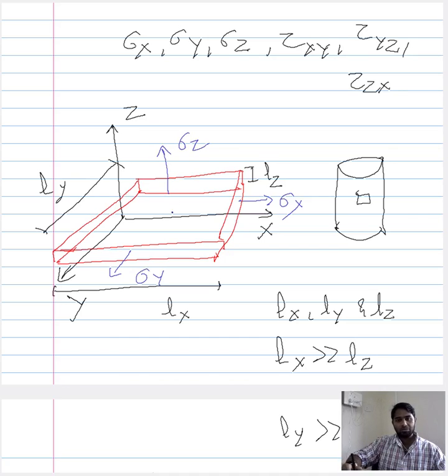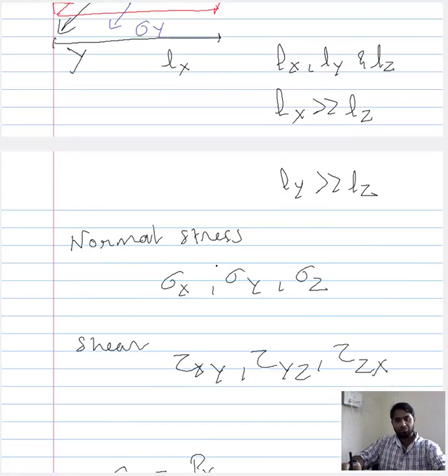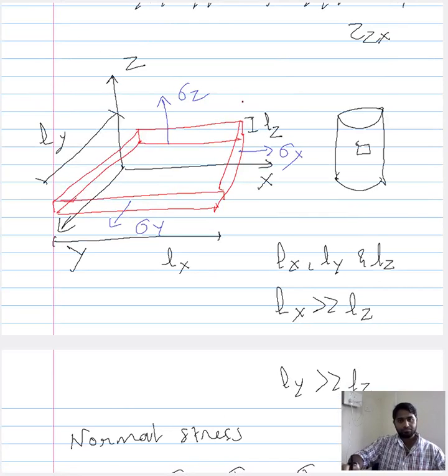Now if you notice, compare the area that is relevant to normal stress component y with the area that is relevant to normal stress component z. We have a normal stress component x, and this is dependent on a particular area. You can write it as P along x, that is the load along x, and the corresponding area that is perpendicular. So this would be this area. We are talking about this area for the normal stress component along x.